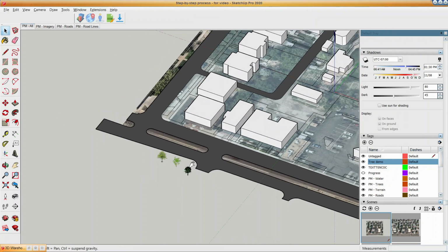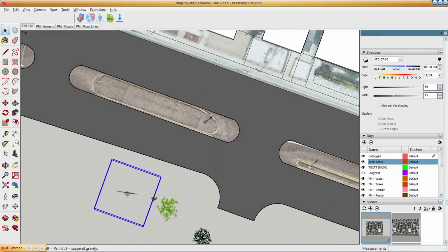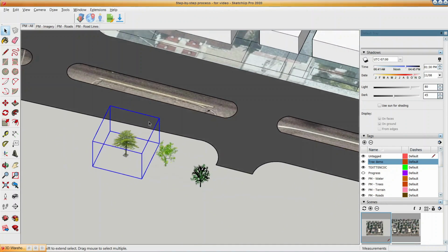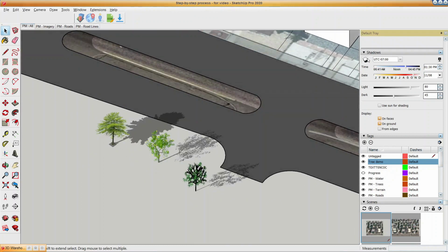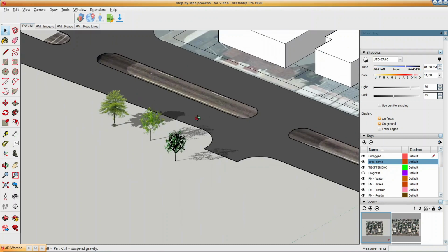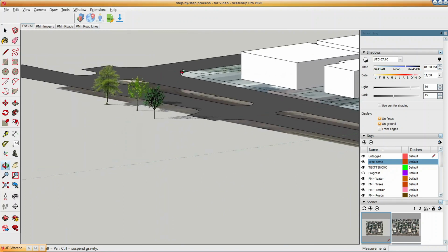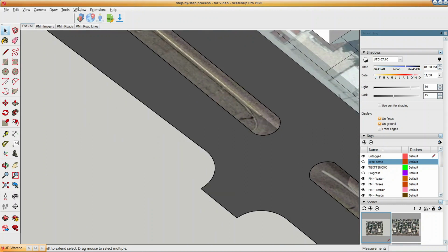If your team decides to use SketchUp as your top view master plan, I wouldn't choose the 2D trees because they will end up being lines when you set it to top view. For 3D perspective views, 2D trees work just fine and generate shadows pretty accurately. Also, some groups might prefer not to use trees from SketchUp and prefer adding them in Photoshop due to texture preferences, which is totally doable. I would say that a big advantage for adding the trees straight from SketchUp is that most of the proportions will be accurate, and so will all the shadow patterns.